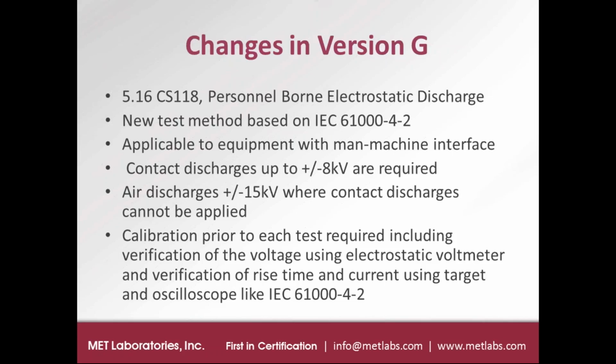And for every test in MIL-STD-461, there's some type of, they either call it a system integrity check or a verification or calibration. All those checks, and ESD has it as well, are some kind of check to make sure the test equipment is working accurately and properly right before each time that the test method is performed. So for CS118 ESD, there's a special electrostatic voltmeter that's used to measure the voltage of the test generator, and then there's a